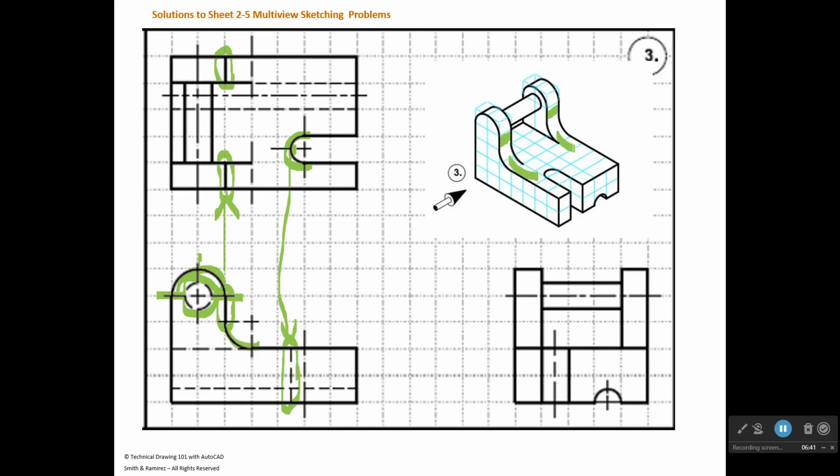Okay, so the other day I think I mentioned that a run out is where you don't have an edge, it just blends in. And so what happens in your top view is you won't have a visible line in the top view for the run out, but you do have a center axis for this round shape that you have here. So that's what you're seeing right here. That's a center line, and this is a center line up there. Okay.